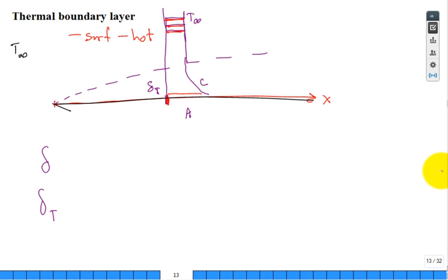But because the boundary condition doesn't start at 0, what we want to do is introduce something else. It's theta, or the book will sometimes use T asterisk. It's a dimensionless temperature difference ratio. Okay? If we want theta at the surface to be 0, how about putting T minus Ts in the numerator?